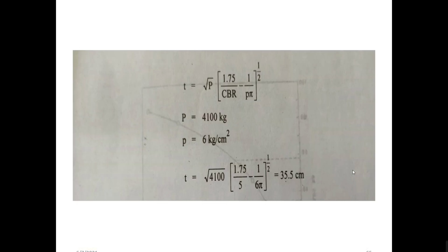It's a very important formula which you have to remember. If in the examination they ask you to design the thickness of flexible pavement based on CBR, then with simple substitution, you can easily determine the thickness.